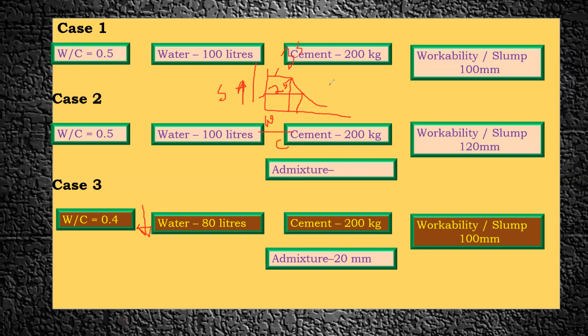That is the reason why in most construction, we try to make use of the admixture. These are the benefits of using the admixture, and this is how the admixture is going to have its effect on the workability, right? I hope this basic understanding about the admixture is clear. That is why, when we were learning the first chapter, we had seen how the plasticizer is going to improve the workability, right? Because always remember, if I lower my water cement ratio, my strength is going to increase.